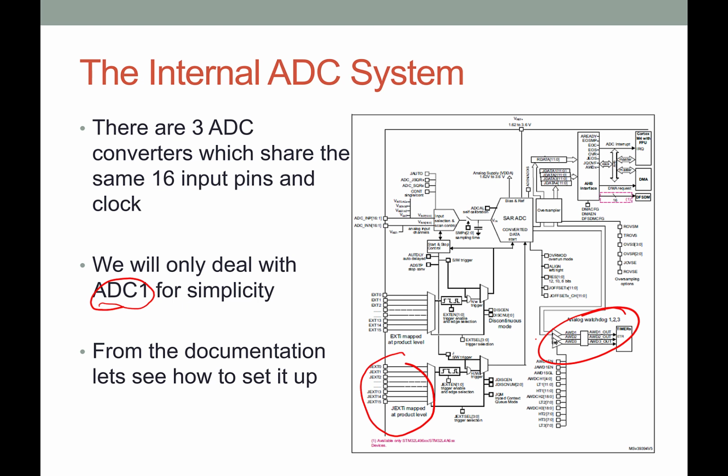Well, that's talking about if you have a voltage that's higher than the high reference voltage or lower than the low reference voltage, that can select the watchdog, which can then run an interrupt that says, oh, something's going on. Because most of the time that means, hey, I've got an analog input that I completely didn't expect to get. Something is going wrong in the system. So you have a way to execute something based upon that. You can see other things with the ones that we're going to do here.